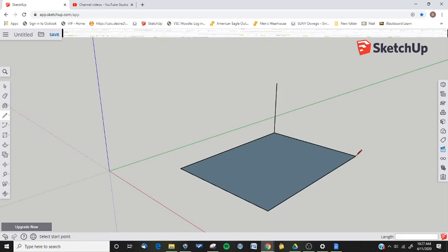I'm going to hit escape because each time I'm going to create a line that is independent and not continuous, like we were doing when I first showed you. So I'm going to hit escape again. You see how blue, and then I'm looking for that dotted line. That one's a little bit faint. I hope you were able to see it. Escape, and then blue, and there we go. Okay, so I've got 4 vertical lines. They should each be perpendicular to the corner here. They should all be the same height because we used that dotted guide line.